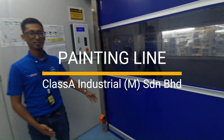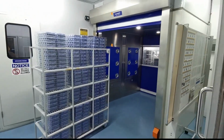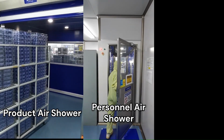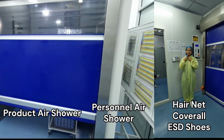Welcome to painting line. It is designed as a control area which separates the 100K and 10K cleanroom areas. Painting entrance is equipped with air shower for the product movement and personnel. It is compulsory for workers to wear proper PPE such as hairnet, full coverall, and ESD shoes.